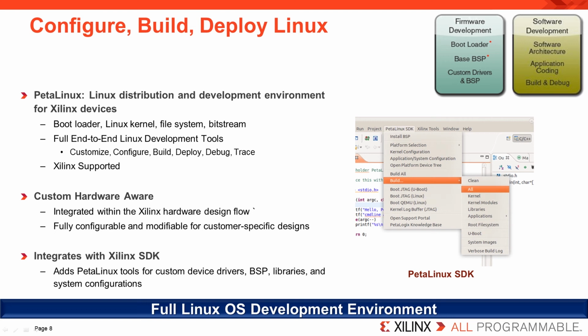Petalinux also includes a fast, functional QEMU system model of the Zynq processing system. Now, software development can take place even before physical hardware is available. Like the automatically generated Linux BSP, QEMU is also configured for the custom design defined in XPS.